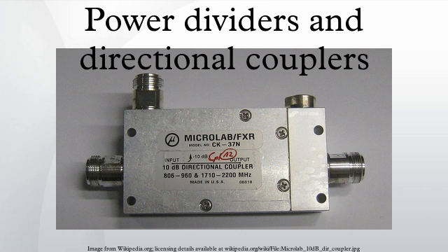A better solution for microstrip is a coupled line much shorter than λ/4, shown in Figure 5. But this has the disadvantage of a coupling factor which rises noticeably with frequency. A variation of this design sometimes encountered has the coupled line a higher impedance than the main line, such as shown in Figure 6. This design is advantageous where the coupler is being fed to a detector for power monitoring. The higher impedance line results in a higher RF voltage for a given main line power, making the work of the detector diode easier.